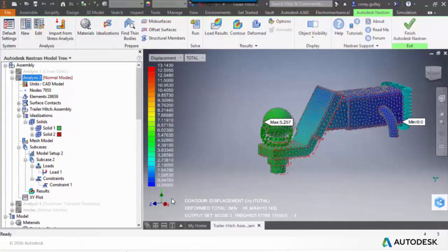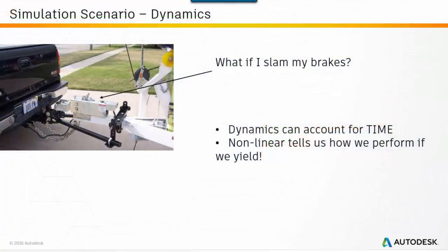In this case, our first mode was at 480 hertz, and then we saw that mode shape move up and down. What we could do inside of an in-CAD environment, if I needed to move that outside of the operating range, is easily jump back over to my modeling environment, and then put a stiffening rib there and stiffen up my structure so that I can move that first natural frequency out, so I don't observe any resonance phenomena. So that's one of the benefits that you get whenever you look at this particular type of behavior.